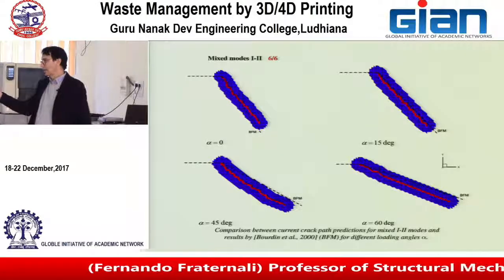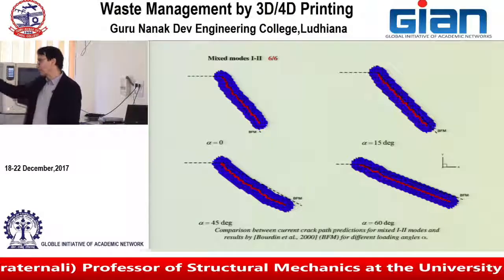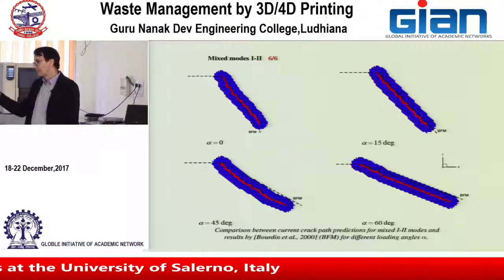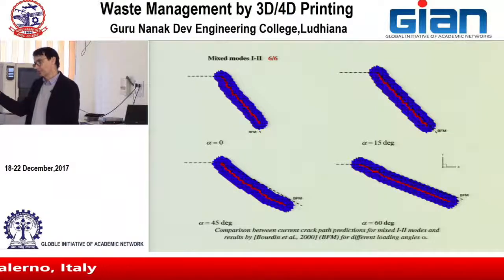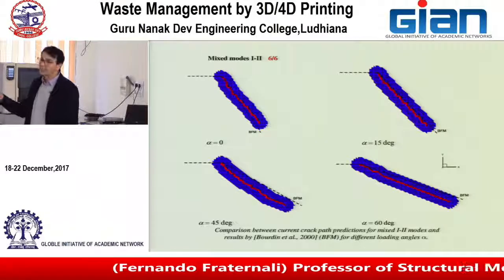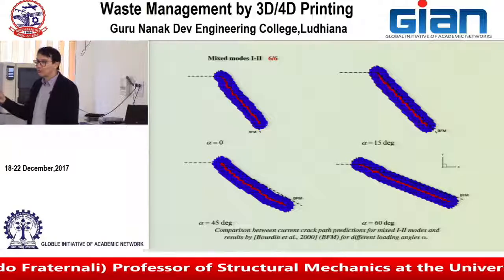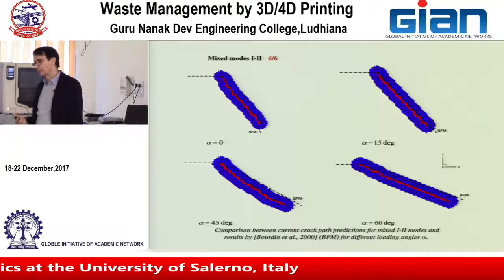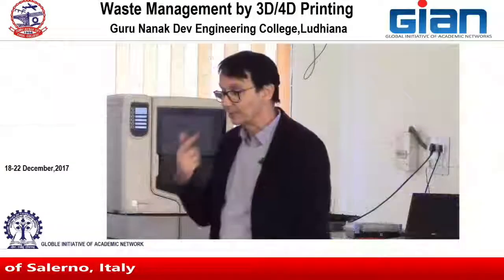It's the size of the elements, the largest size of the element in the process zone. You take epsilon 3, 4, 5 times this h, and then you use epsilon in the form that I described.